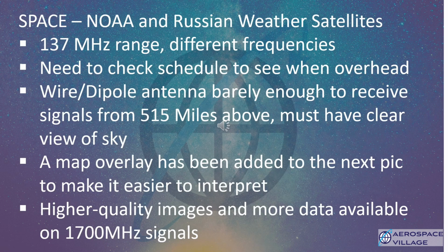Using your badge or other simple antenna, you can download signals directly from satellites right to your PC. You'll have to check the schedule and see what time they're going to pass overhead. Get your antenna outside with no obstructions, and you have a good chance of receiving a great map from a satellite.